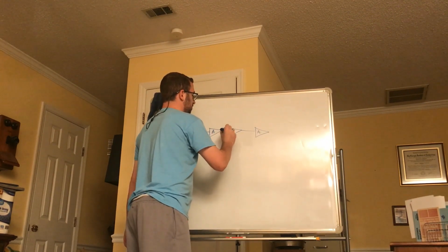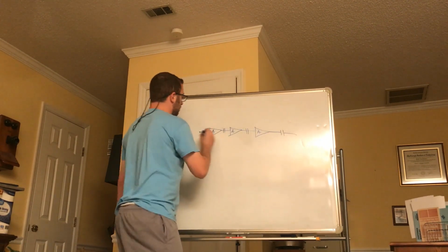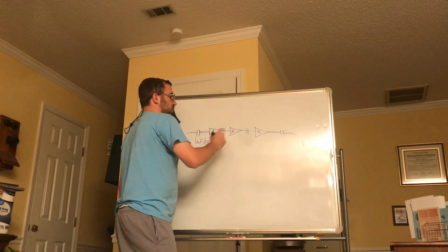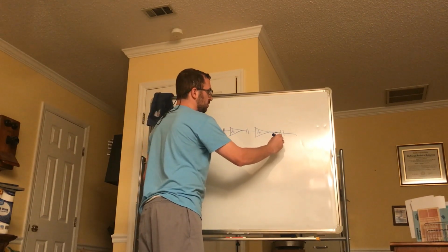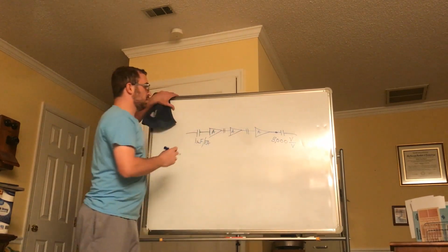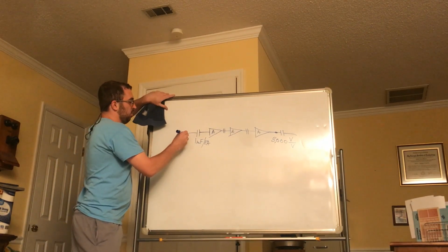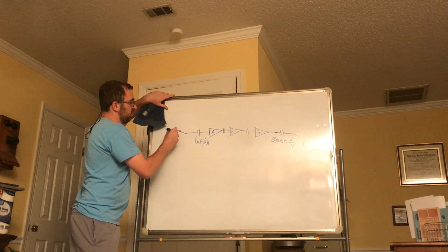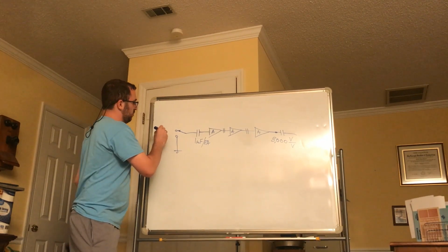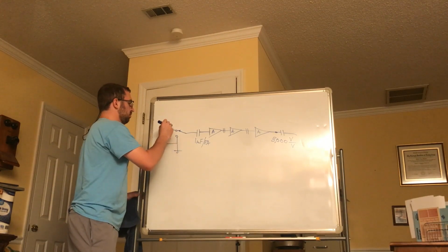Of course, these are actually filter caps, but they act as shorts at signal frequencies. Your final cap, your input. These were all 1 microfarad. So your total gain here is 8,000 volts per volt per the math earlier. But you might wonder how it's possible to get direct current amplification when these only pass AC. Well, the answer is really simple. You just have a relay here, and this would be ground, and this would be your input DC. Probably have a capacitor here to filter it, so only the DC gets through.